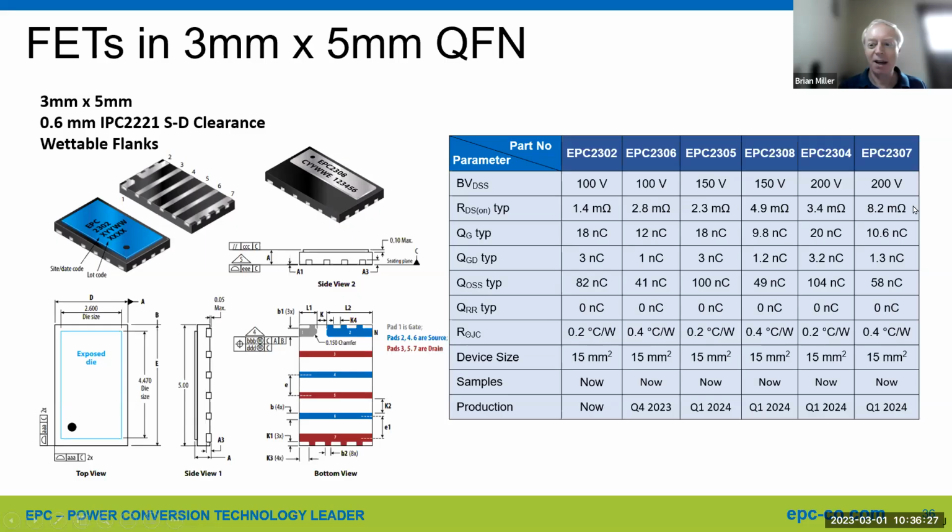You can see it doesn't take a whole lot of FETs in parallel to make a very good high current, low loss parallel system. And especially with the gate charge being low, even with such low RDS(on), the gate drivers are able to handle that pretty well. So these kind of FETs would be popular for some of the previous motor drive applications, power tools, eMobility, and so forth.